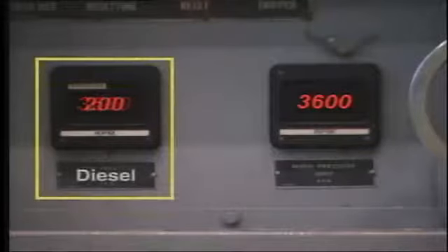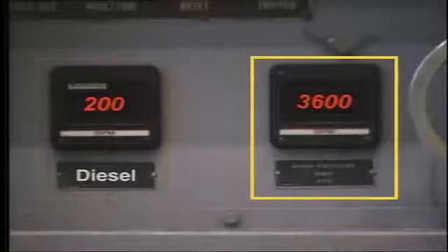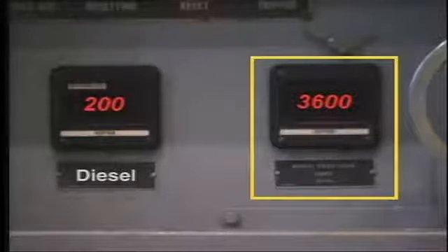The steam turbine runs at high speed, usually 3,600 RPM in North America or 3,000 RPM in Europe, and can therefore be coupled directly to a two-pole generator. Remembering that the diesel engine operates at around 200 RPM, we can see one of the reasons why the specific output of the steam turbine is much greater.